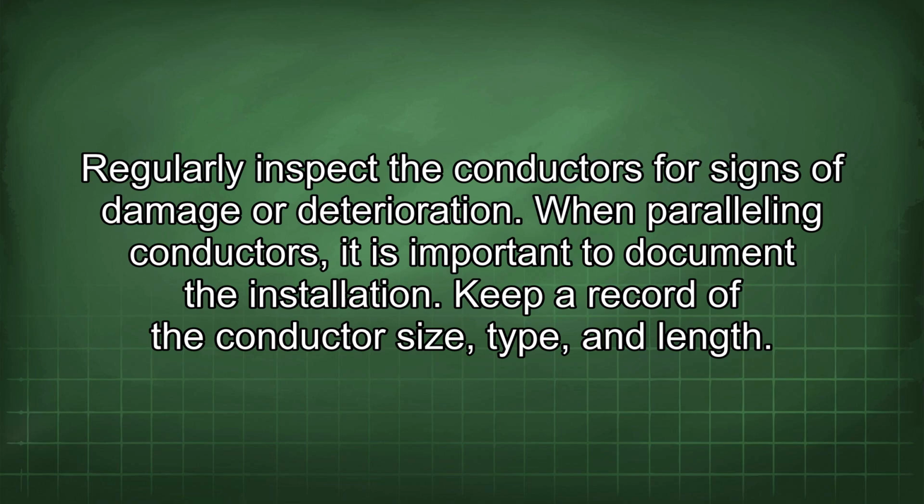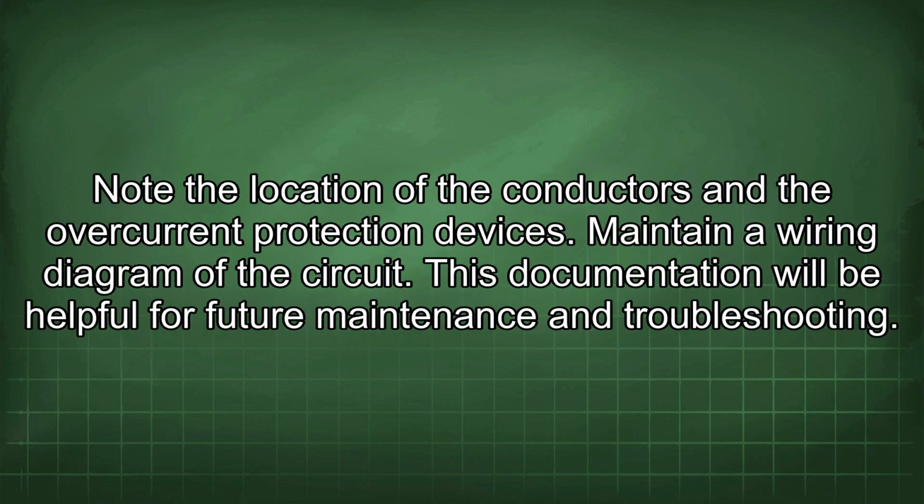When paralleling conductors, it is important to document the installation. Keep a record of the conductor size, type, and length. Note the location of the conductors and the overcurrent protection devices. Maintain a wiring diagram of the circuit. This documentation will be helpful for future maintenance and troubleshooting.